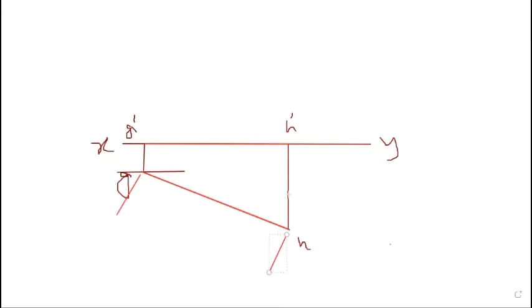And if we use the unidirectional system, the 50 will be positioned at the middle of the line. You just erase this portion, write 50, and here you draw the arrowhead according to the 3:1 ratio. So this is the projection of problem number 2.